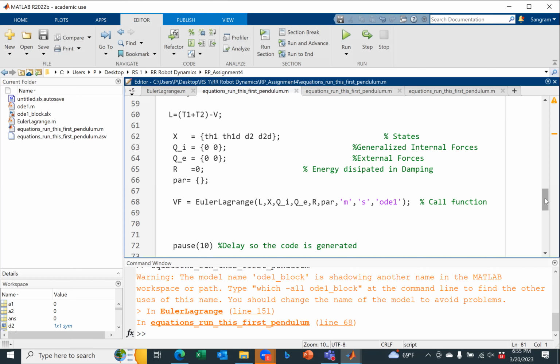D2 is a function of time, cosine theta is a function of time. So I get D2 times minus sine theta 1 dot plus D2 dot cosine theta 1, plus L1 is a constant, L1 sine theta 1 dot. Are you with me?